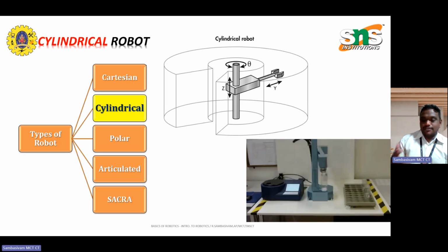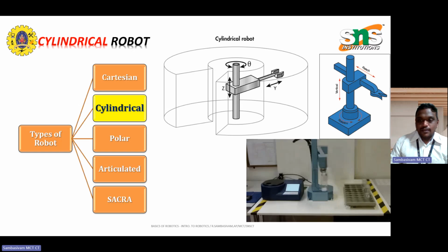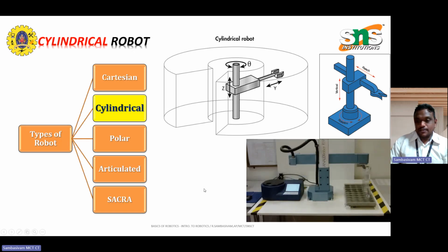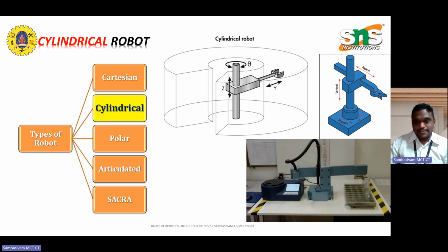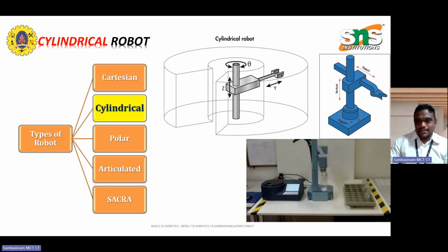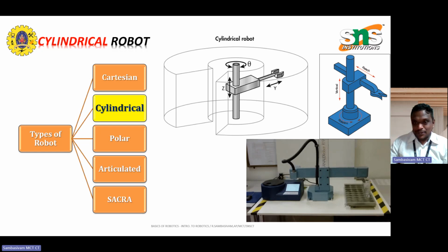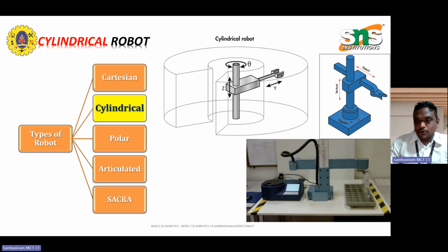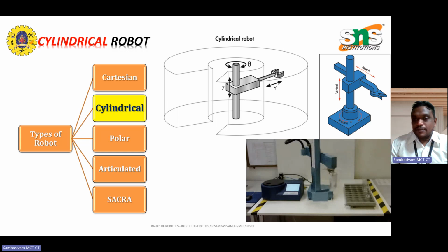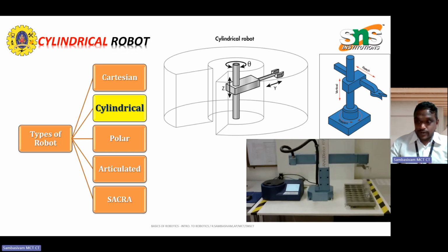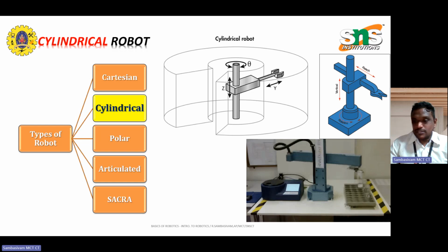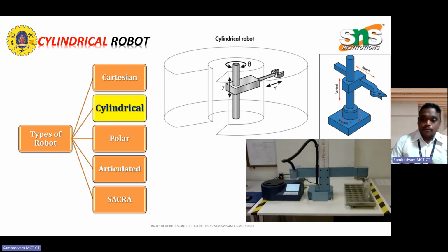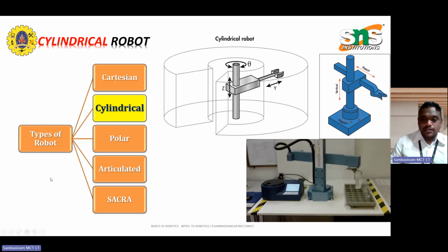Instead of explaining everything, I would like to share the presentation on how it is done. See the presentation. So how is it moving? Everybody has come to know something about it. The rotation has been included as compared to the previous Cartesian. So there are two linear motions, one vertical and one horizontal, and the third motion is the rotation. The picture on the upper right shows one motion to reach, one vertical movement up and down, and another one is rotation. The zip file shows a bottle being taken, moved for weighing, and returned to its original position. This is how cylindrical robots work.